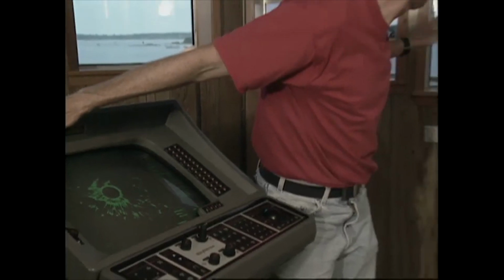If we look out there, we can see that the boat that I marked was actually the 12-meter yacht Shamrock, which is moored in the harbor next to us here at the dock. We've talked about techniques for measuring distance using acoustic waves and radio waves, but you can also use time-of-flight techniques with light or infrared radiation. And in fact, much of the equipment that's used for land surveying uses time-of-flight techniques of infrared radiation.